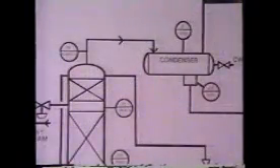As the mixture in the column vaporizes, this vapor rises to the top of the column, where it's routed to the condenser. In the condenser, the vapor is cooled and returned to a liquid state. Part of this liquid will be sent back to the column as reflux. The inside operator monitors the reflux level in the condenser leg. As soon as the level indicator shows that reflux is accumulating, he tells the outside operator to start the reflux pump. At the same time, he sets the reflux flow control valve to a flow rate specified by the system operating guidelines.